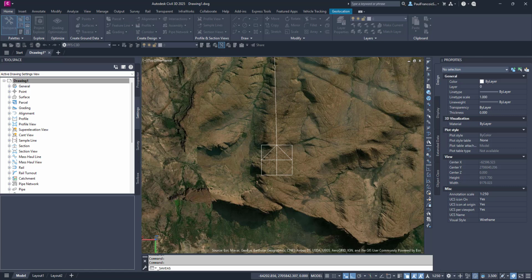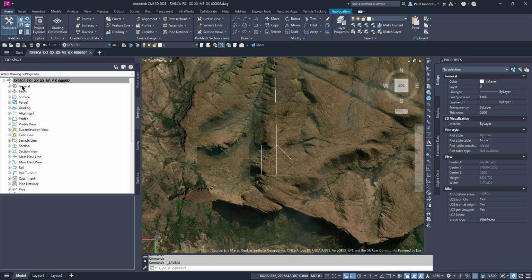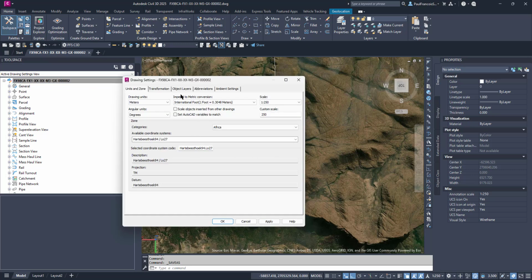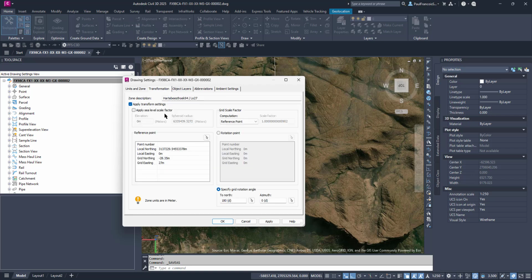And now the next thing we need to do is in South Africa, we need to do a coordinate transform. It's also on the settings tab. Right click over there, edit the drawing settings. So if you want to do this correctly, without error, switch on the transform. Say here that the reference point is 0, 0, 0. That you're rotating about the 0 point, and a reference angle first of 90. So we first go with 90.